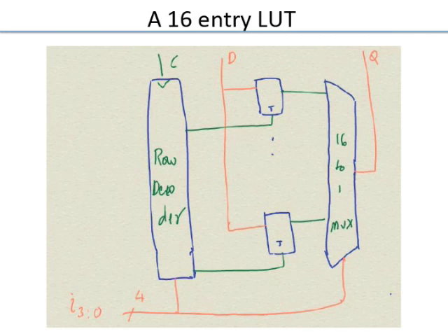It has to go on and then shut off. I'm creating that pulse by just ANDing it with the clock, because the clock is already like a pulse. Of course, the pulse width is exactly 50% of the clock period most of the time, but I don't have to do anything extra. So really, all you do is AND the clock. Clock becomes another signal to your decoder.